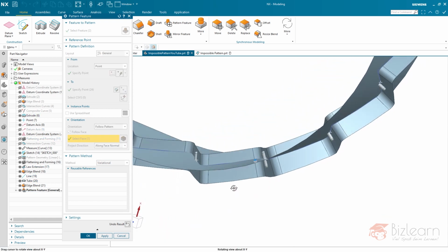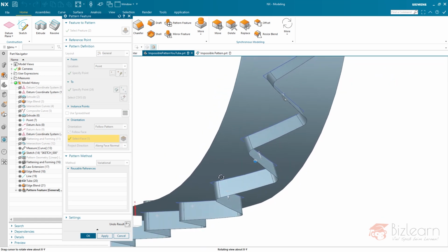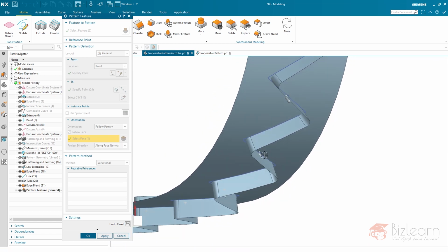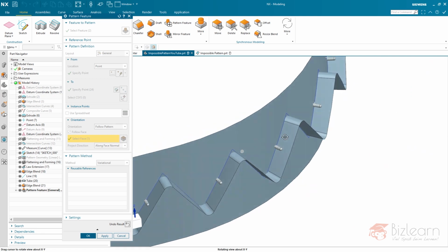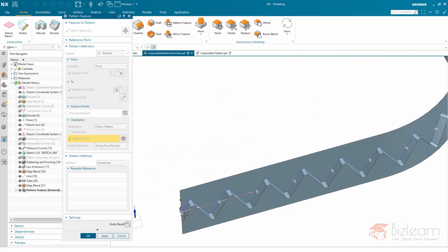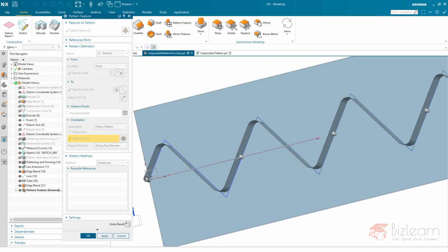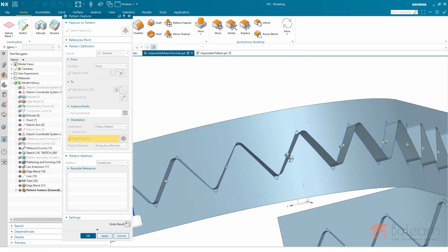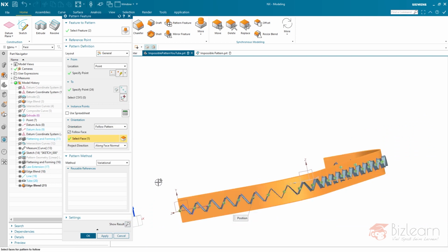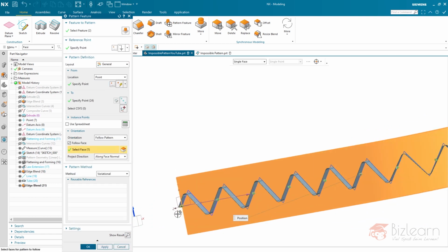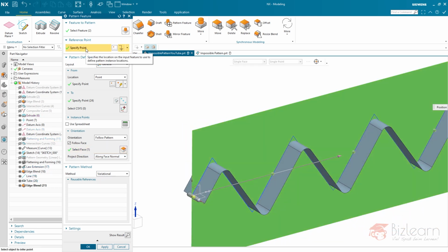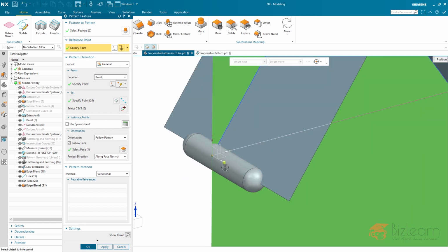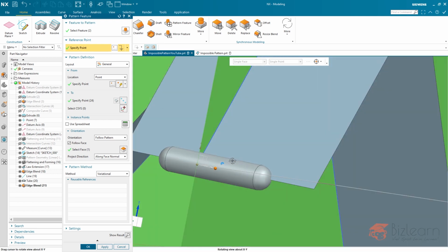As you can see, this is another option to create this, but just have a look. Can you see this? If you don't have a straight and detailed look, it looks fine, but it's not. Here it is exactly center aligned, but in the curve, it's not. One of the reasons is the reference point. Because each time a pattern shall follow a face, the reference point needs to align with the face, but it's not. This one is aligning the face, but this one is somewhere else.